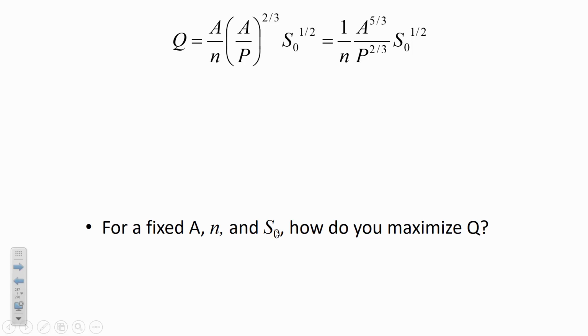So a hydraulic designer can't say, well, let's just make the stream steeper, and then it will carry plenty of water, because if you make the stream steeper, then it's going to go underground, and that's not realistic. You can't have your river getting deeper and deeper and deeper compared to the surrounding land, especially because eventually that water is going to have to match up with whatever is accepting the flow. And so maybe it's a lake, maybe it's the ocean, so you can't have the river below the ocean when you get to the coast.